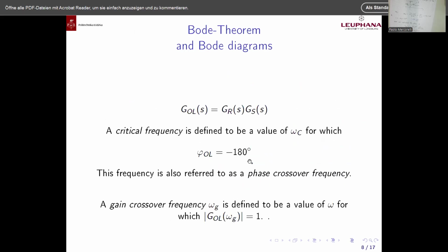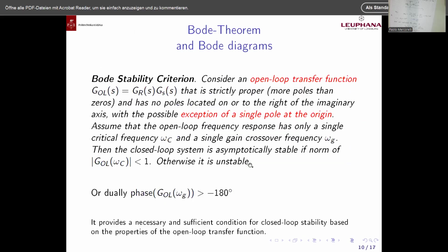We have an important theorem, which is the Bode stability theorem, which tries to quantify how critical our control loop is, considering just the open loop system or the open loop structure, GOL. Moreover, this Bode stability criterion does not consider S, but just omega.